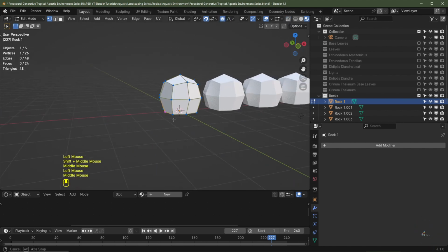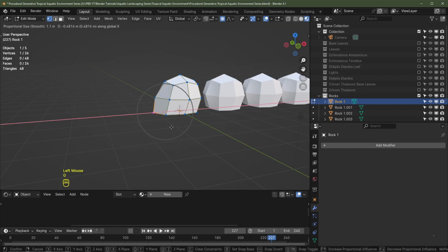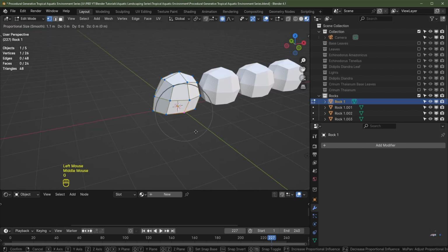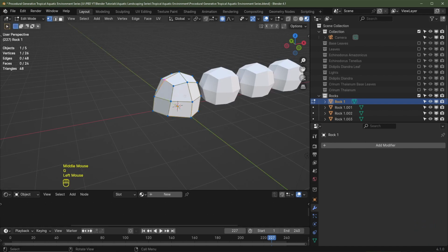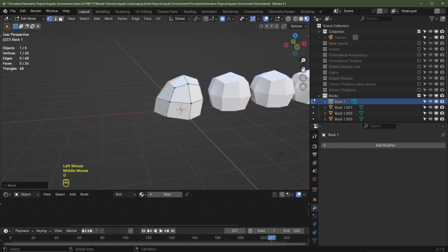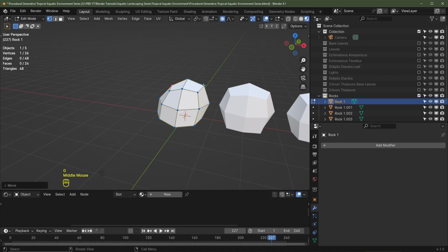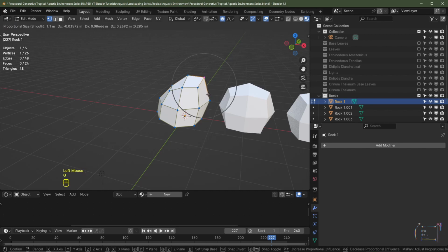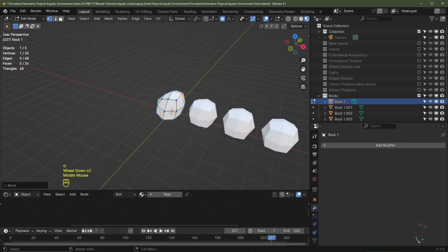I'll just grab this vertex here. I'll turn off snapping. I'll just hit G, X. I'm going to drag this out to maybe round about there. Drag this one on the Y-axis, G, Y. Maybe I could bring this one in, G, bring that into there, and possibly hit G. We'll just drag this up to around about there. So you've got a rough shape there.